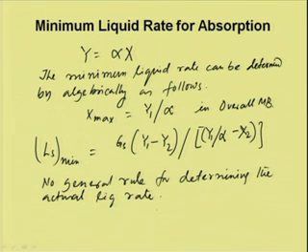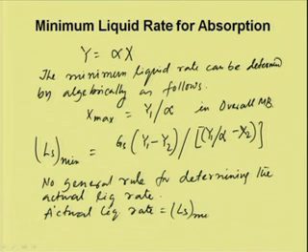In general, the actual liquid rate is equal to Ls minimum times 1.2 to 2.